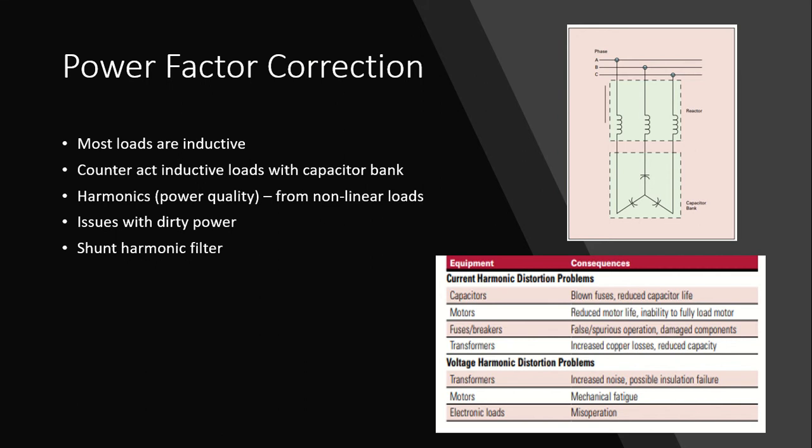However, if you don't know which load is causing the power factor to be bad, or there's more than one load that is causing the power factor to be bad, you can put the capacitor bank in the beginning of the power system.